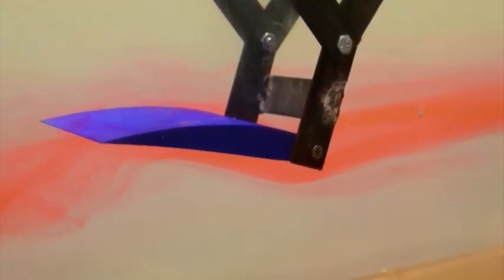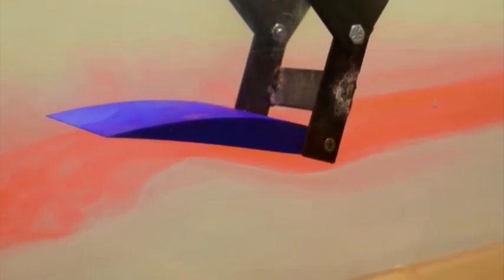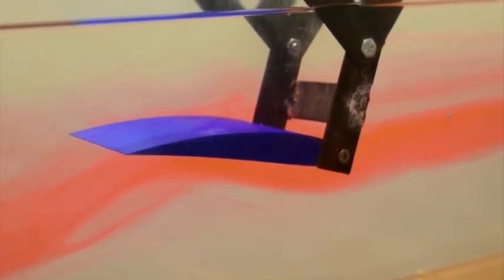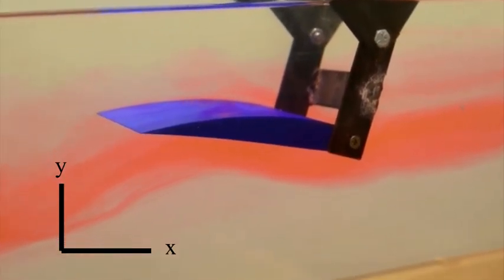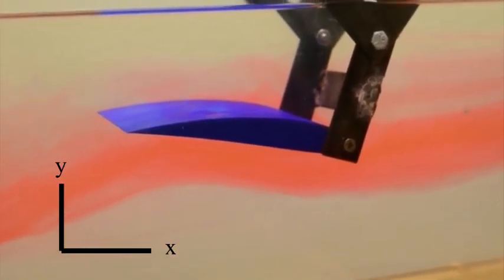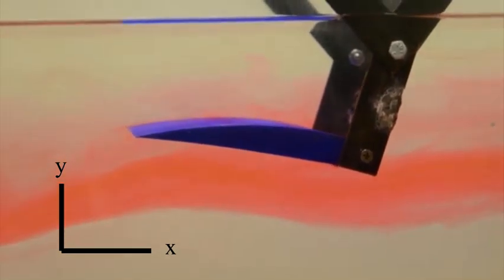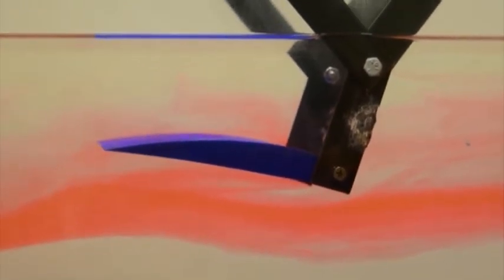For this airfoil, we are only going to be concerned with 2D flow. Like I said before, streamlines are always tangent to the instantaneous velocity. The streamline can then be broken down into two components. With traditional x and y axes, it can be seen that the differential change in the x component is equal to u. The differential change in the y component is equal to v.